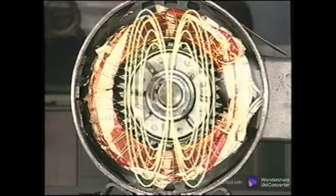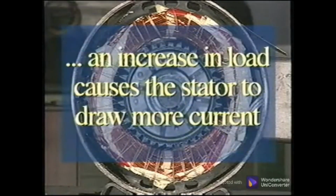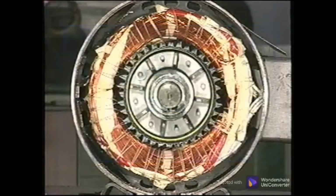To increase torque, there must be a greater amount of relative motion between the rotor and the revolving field. This is why an increase in load causes the stator to draw more current.